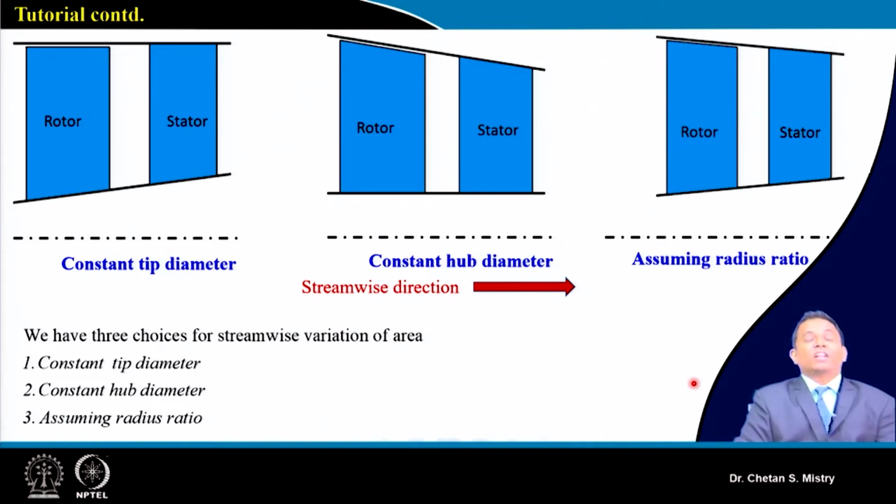Suppose we are considering a low bypass ratio engine, where you may have more than one axial flow fan on the LP spool. Under that configuration, based on downstream requirements, meaning what connecting duct we will have for the LP spool and HP spool, that needs to be done in an aggressive way, and as per your requirement you may need to modify and design different configurations.